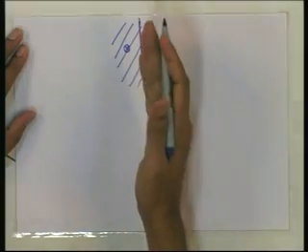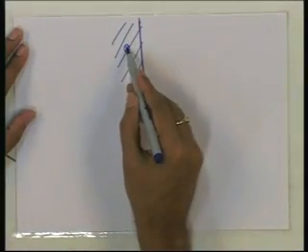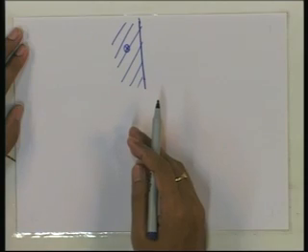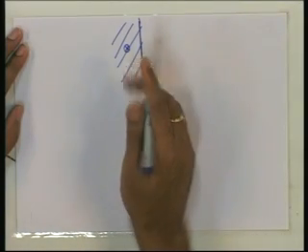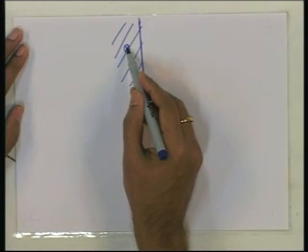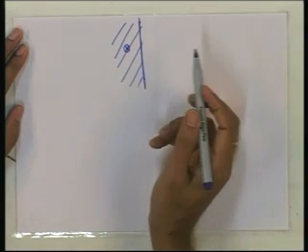That is, if the received point is on this side of this line, then we detect this point, otherwise we detect some other point. Then what will be the probability of error for this point? We are transmitting this point and we have to find out what is the probability that the received point will be on the right hand side of this line.